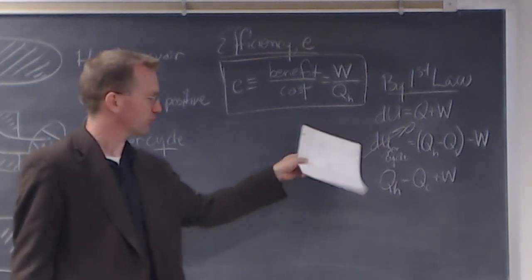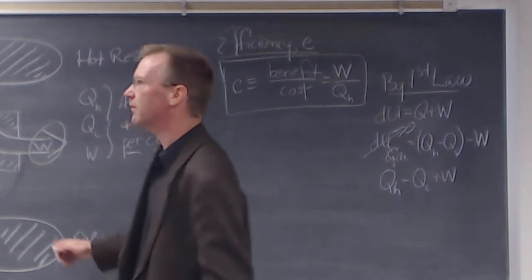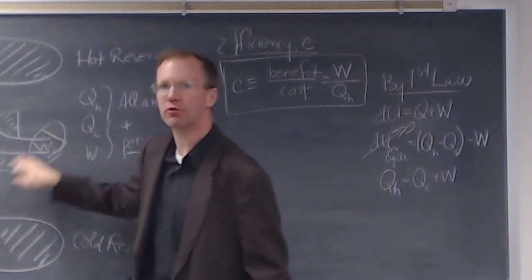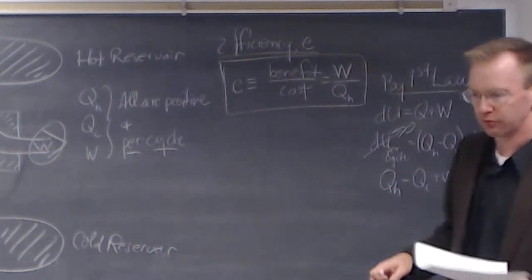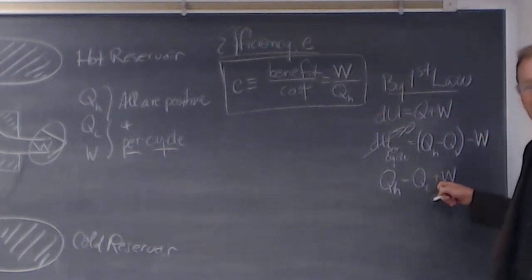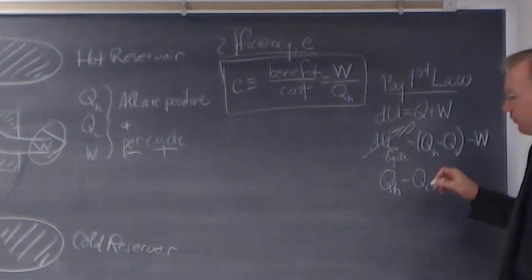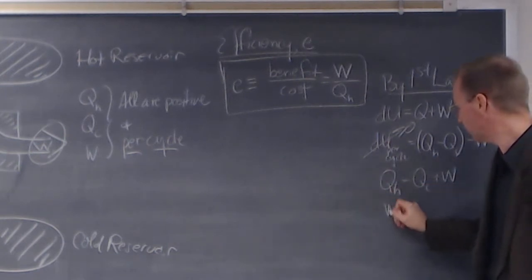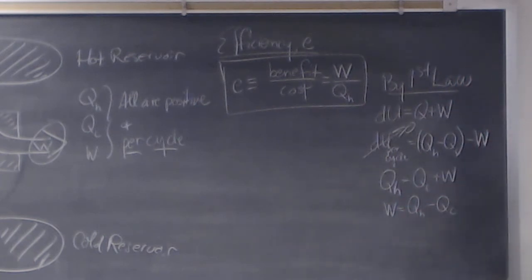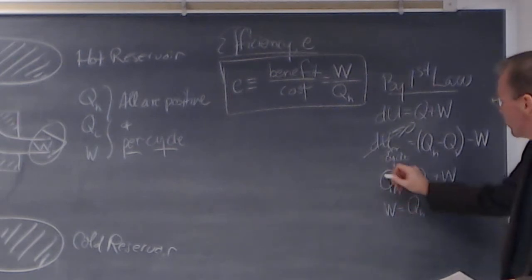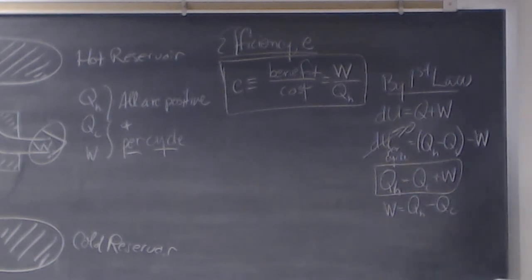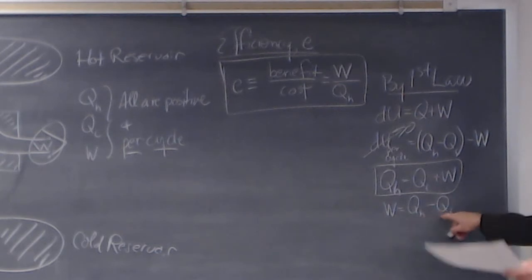We had to say that it returns to its starting point, and then we get the fact that the total coming in equals the amount going out by both of these channels: waste heat and through work. Okay, good. Also means we can solve for W, the work done out, in terms of the difference of the heat flow. Nice. By the way, I really ought to box that in. That's a useful relationship to keep in mind. Okay, so the work done equals QH minus QC.